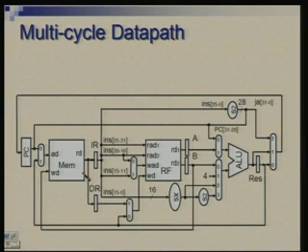All the registers may not change their states in every cycle. So, each register will have a signal indicating when we write something into those registers. We have controls for the multiplexers as usual, and similarly controls for ALU, register file and memory. But since we have new components like registers, and multiplexers have either changed in their size or in their organization, we will have to redefine some of these control signals.